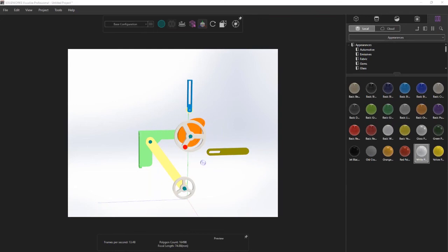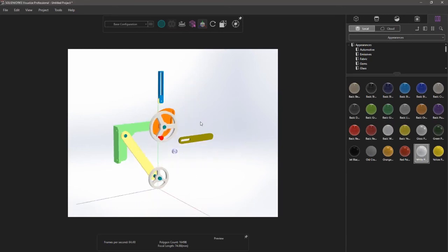Good question from James here. Is the image quality, missed part of it, just why are we reducing image quality? Simply to stay under the VRAM limit. Yeah, so I wouldn't bother reducing this unless you were seeing performance issues, right? If you're seeing performance issues, then you want to pay more attention to reducing your image quality. But as you see, millions of polygons are fine. Don't cause issues until you get to that limit where all of a sudden now you're running out of memory.